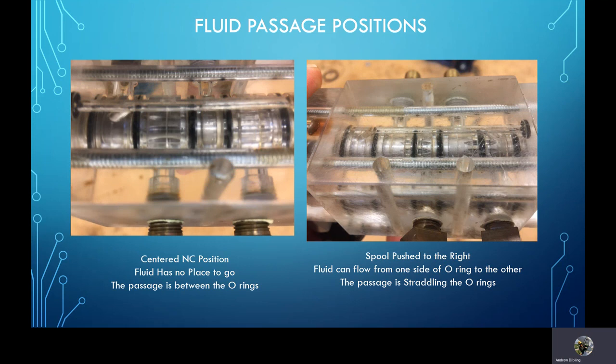Now, you'll see that there's really not a lot of fluid that's going through there that will activate your motor or your piston. Now, mind you, there are a lot of little fluid passages, about 10 or 12 around the diameter of that spool valve, but still, compared to the inside diameter of the conductor, it is a little bit of a pressure restriction.